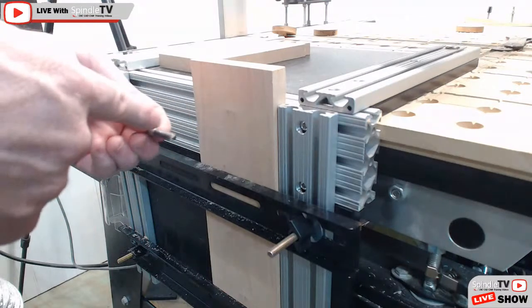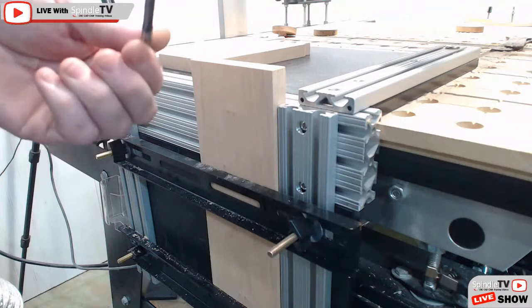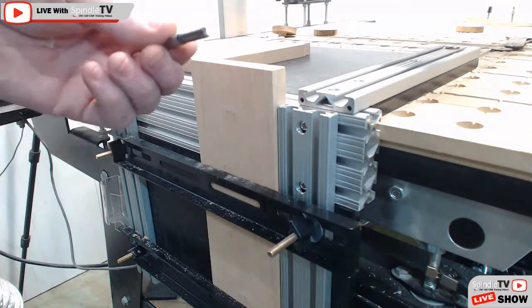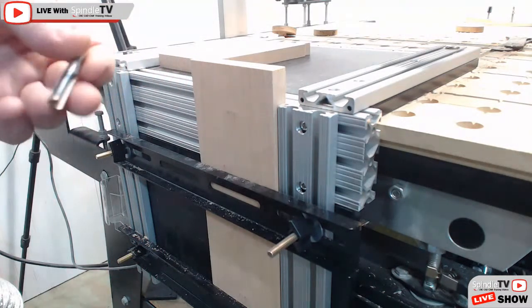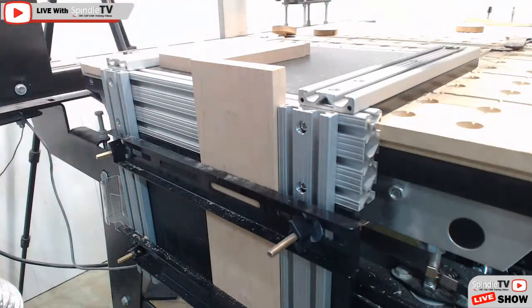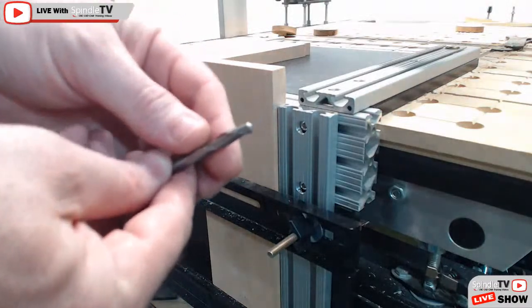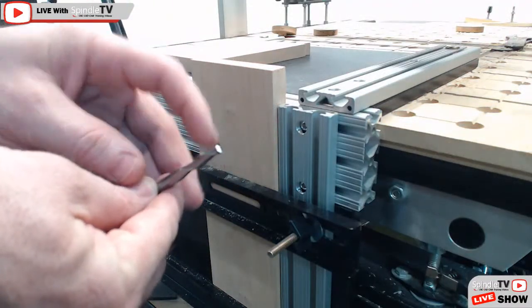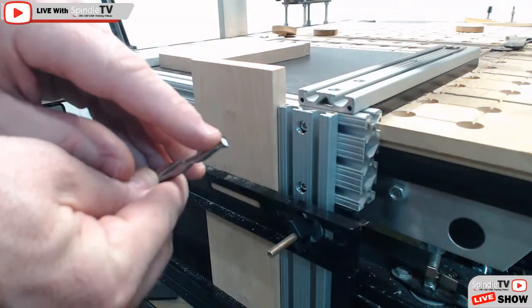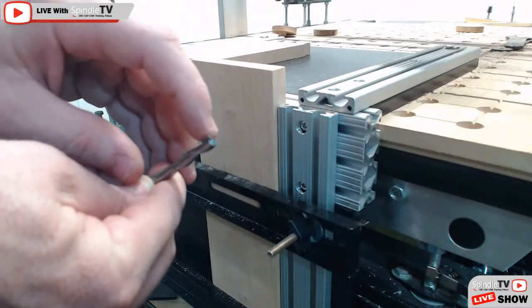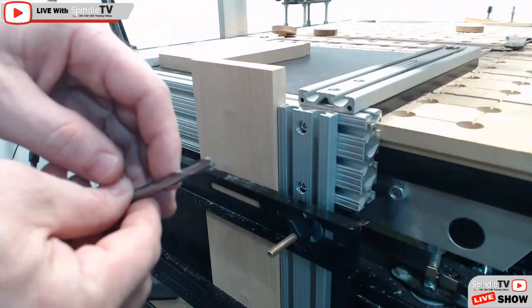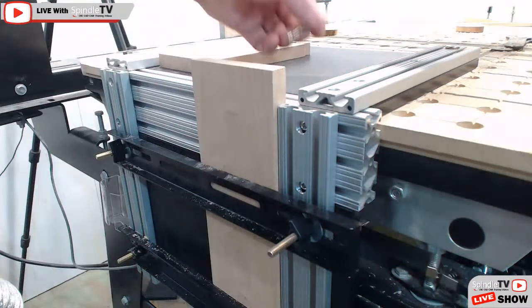And it's a little blurry, but they don't wrap around to the tip. And so therefore it's not really technically a plunging bit. It's more of a ramping bit and everything. On the spiral bit, the cutters wrap to the bottom side as well, so it can be plunged. And that's what we're going to be using.